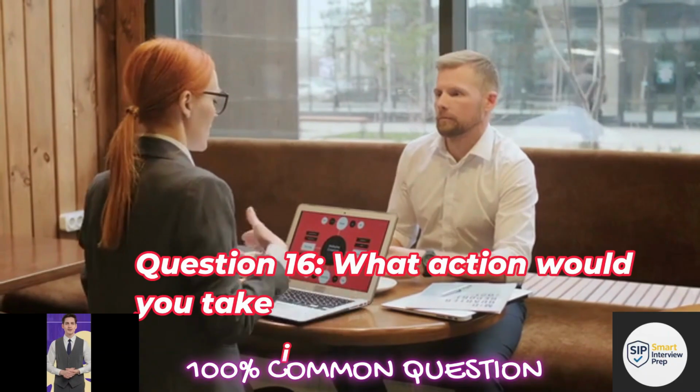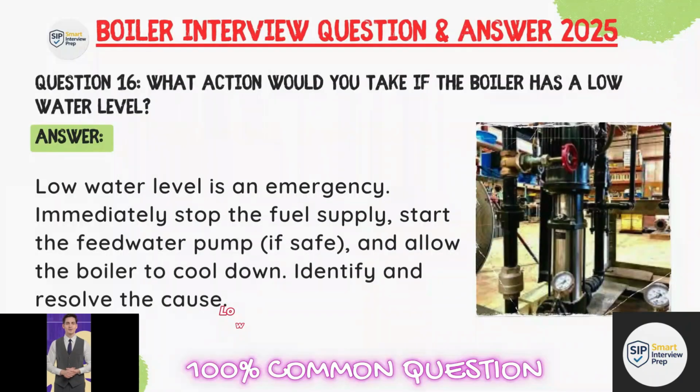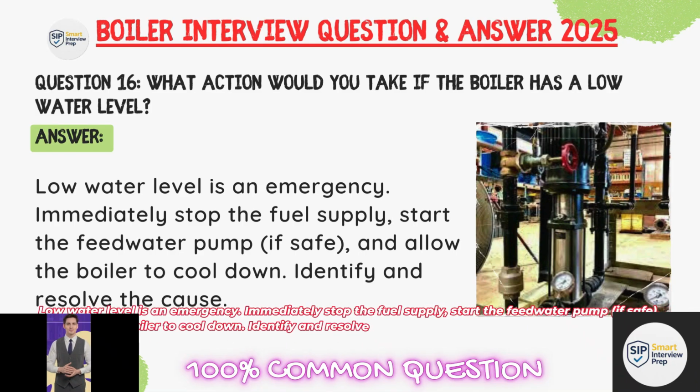Question: What action would you take if the boiler has a low water level? Answer: Low water level is an emergency. Immediately stop the fuel supply. Stop the feed water pump if safe and allow the boiler to cool down. Identify and resolve the cause.